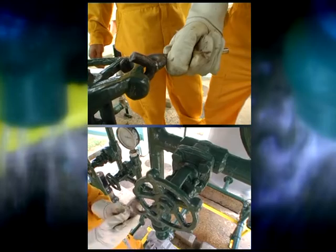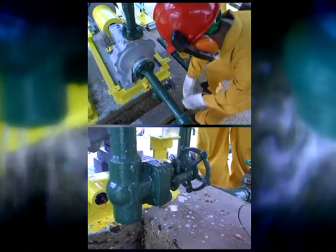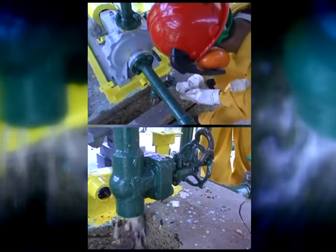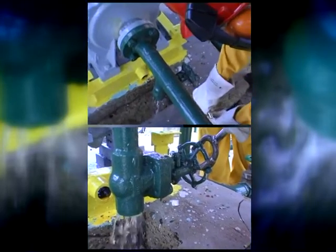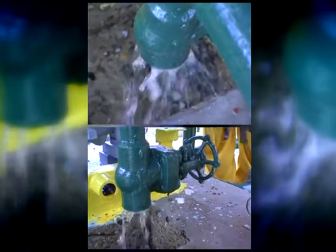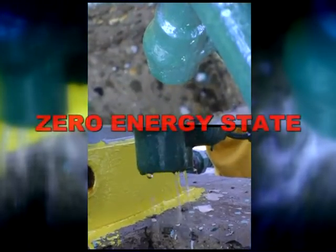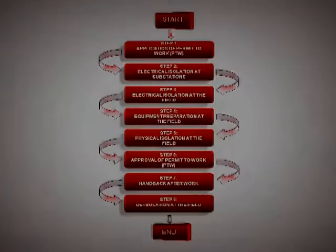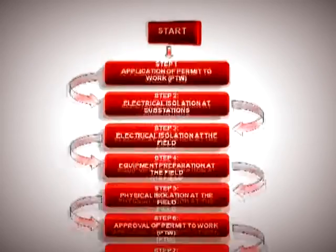The key requirement of energy isolation is to check and ensure all energy sources must be drained, purged, flushed, isolated, and brought down to zero energy state before any work can begin. Let's recap on what we've learned so far.